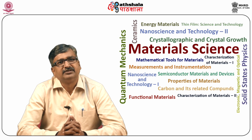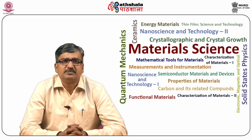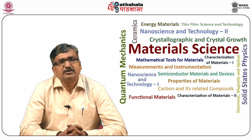In 1953-54 and by Cohen in 1992. Maximum hardness is observed with a mixture of GP2, which is called the corresponding GP zone, and theta dash, with the dimension of the theta dash plates typically about 10 nanometer in thickness by 100 nanometer in diameter. Therefore, the important microstructural features of age-hardened aluminum alloy are on the nanoscale.